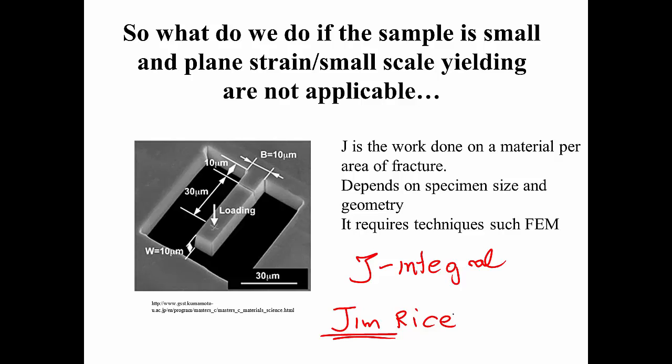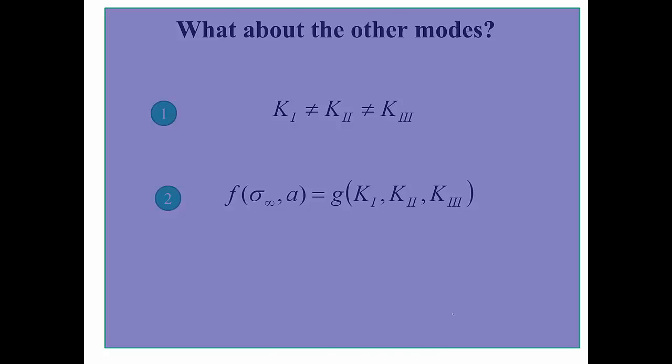It can be applied for specimens and geometries for which the linear elastic fracture mechanics that we discussed is not applicable. So if you ever have to deal with something like this, just go and read more about the J integral technique that helps in those more complicated cases.